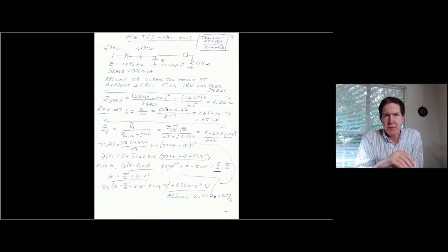And as I mentioned in the theory part, the example is that we have a substation that's converting 69 to 12.47 kV, and it has an impedance of 10%. In this particular case, we'll start off by assuming that there's no resistance to worry about. We have a base power of 25 MVA. That would be the rating of the substation in this case. We're going to use that to convert the per unit value into ohms.